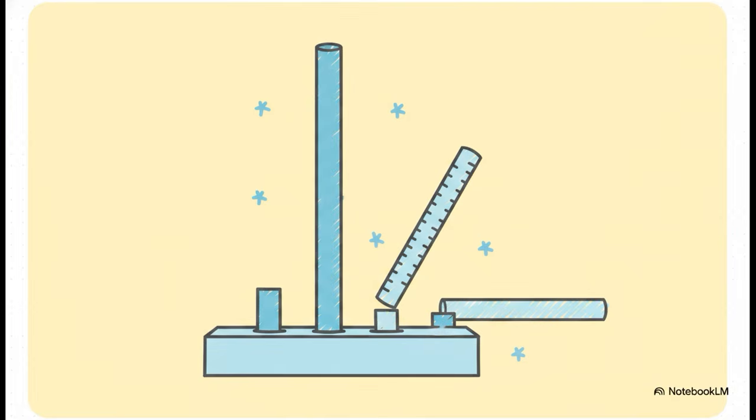Thinking about these 3 together brilliantly illustrates how they interact. Imagine taking a single shaft feature and swapping these callouts sequentially. First, you apply perpendicularity, and boom, the tolerance zone snaps the allowable tilt to perfectly straight up and down at 90 degrees. Then, you swap the symbol out for angularity with a basic angle of 47 degrees. Instantly, the tolerance zone tilts over, allowing the shaft to lean precisely to that angle. Finally, you apply parallelism, and the tolerance zone slams completely shut to 0 degrees, forcing the shaft to lay flat against the reference plane.